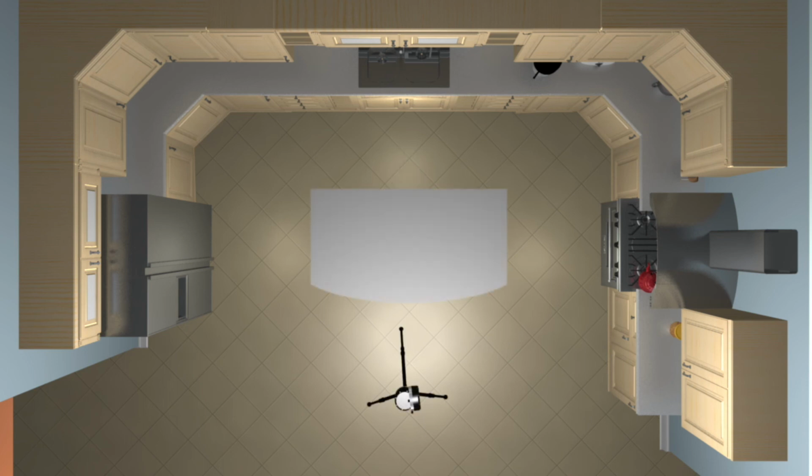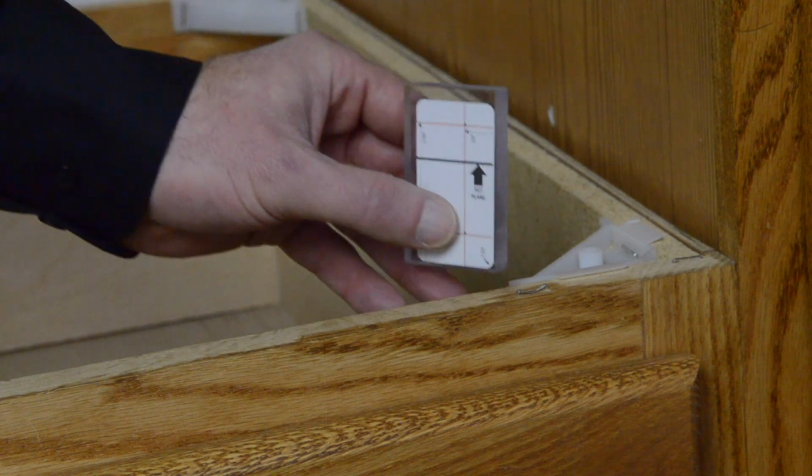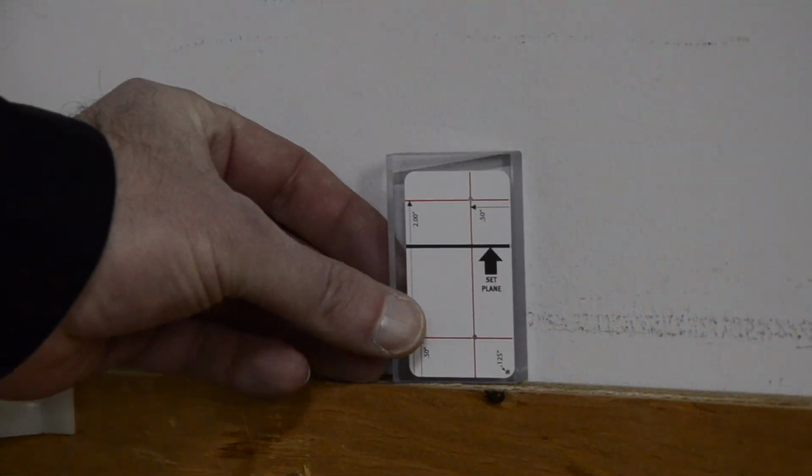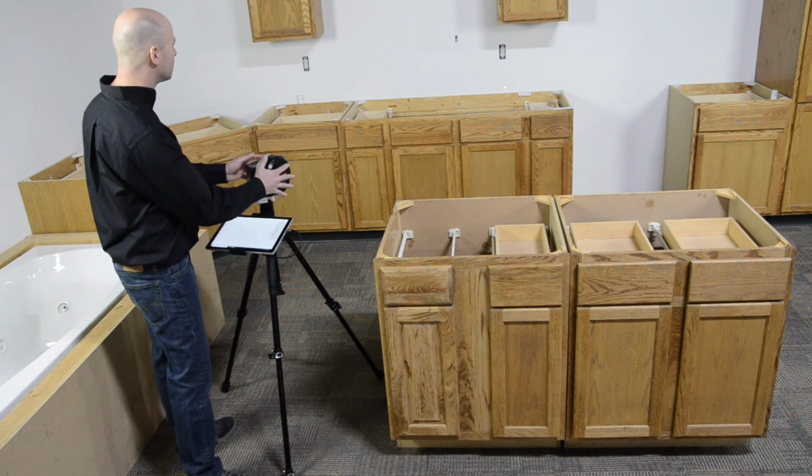Alternate positions may be required based on obstacles and the use of targets. Once the location is determined, set up the laser and position all targets before starting to measure. Now we can start measuring without leaving the laser.